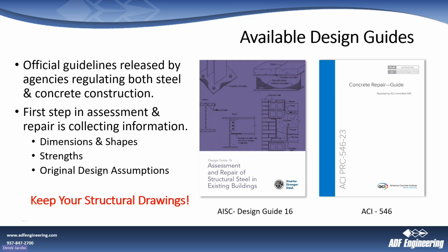The guidelines I'm going to be referencing a little bit, and I did take a couple of pictures from both of these documents, which are pretty helpful. The first one is the AISC, the American Institute of Steel Construction. Their Design Guide 16, which is actually a new version that just came out, addresses the assessment and repair of structural steel in existing buildings. So a lot about what we'll be talking about today. And then ACI, the American Concrete Institute, their guideline 546. It's kind of the same thing on their end, which is the Concrete Repair Guide.